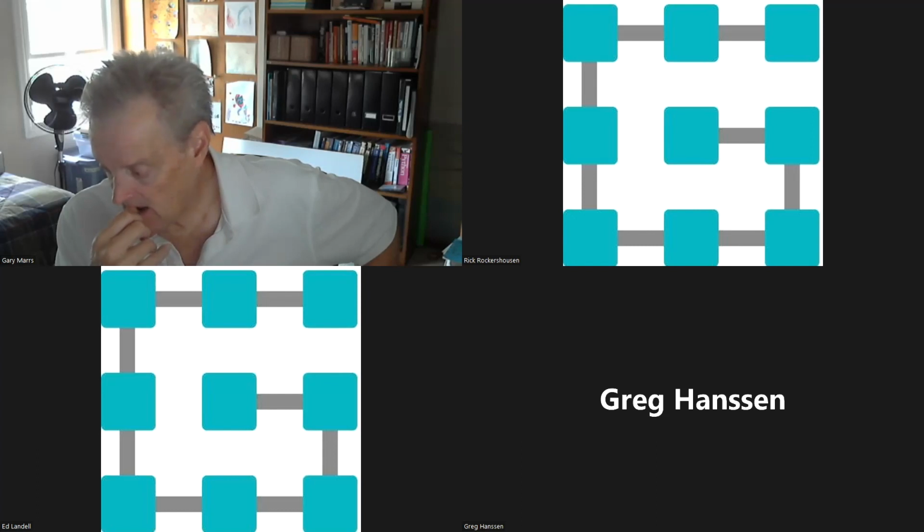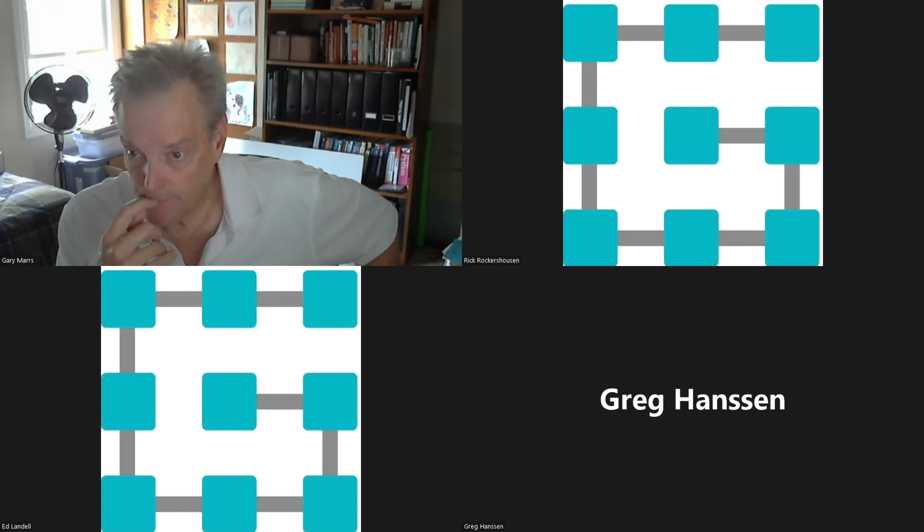Yeah, I think we were only responsible for sending out a single CAN message, and the fact that nobody was responding, acknowledging it, meant that our transceiver, our module, was in constant transmit error mode, and clogging up the bus. And so our only solution was to add yet another node on our side that would just sit there and acknowledge our single message that was going out to the vehicle.